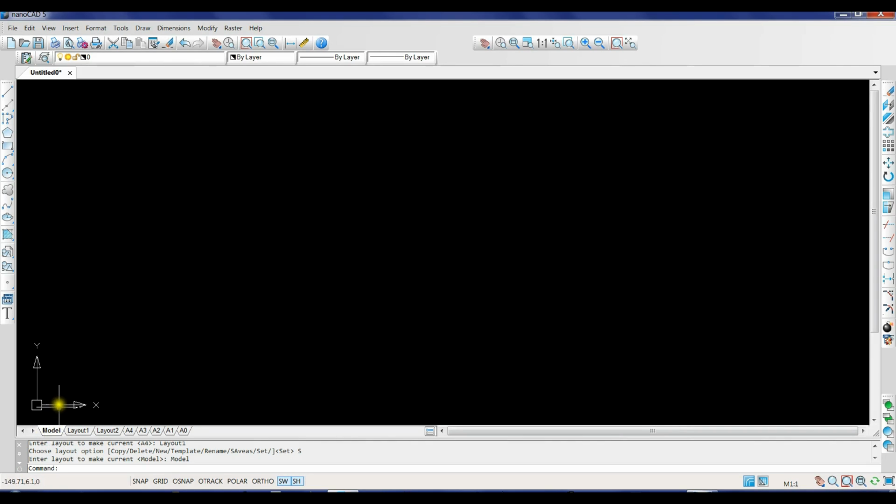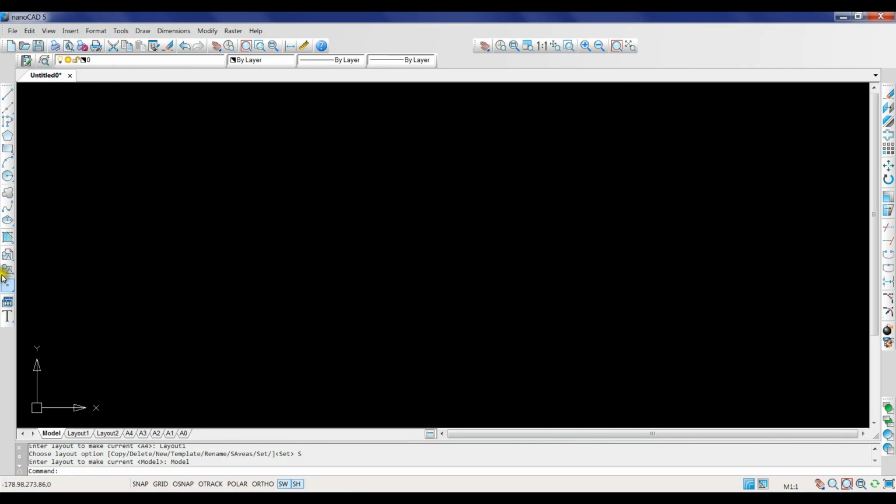Right, what else do we need to look at? The last thing probably is down the bottom left is the command window, and this allows us to put in commands from the keyboard, which are often the same as what you find on the menus or the picture icons, but it's useful to have keyboard stuff for speed, and once you get used to them you can enter lengths and dimensions and all sorts of things in that window, so it'll be quite important as we go forward to keep an eye on that one.